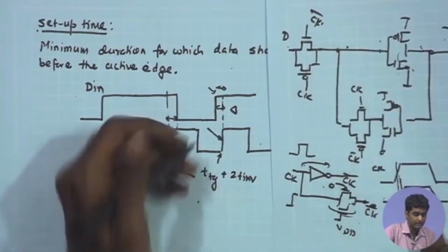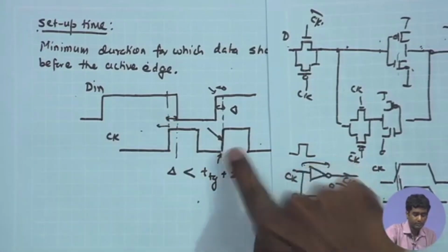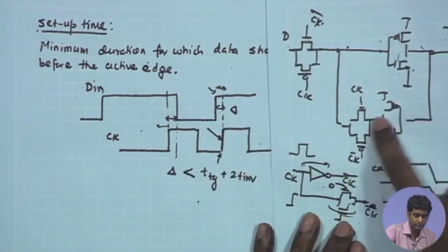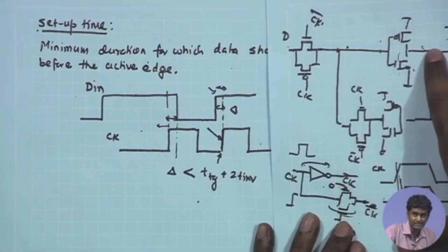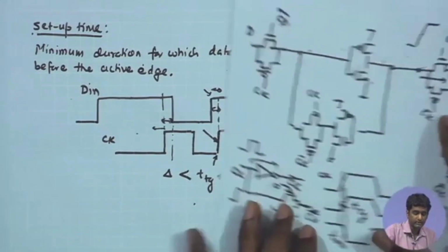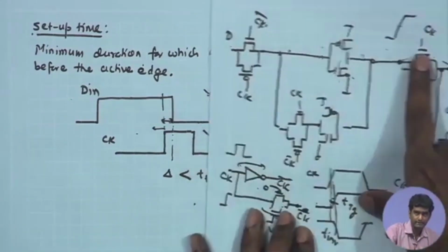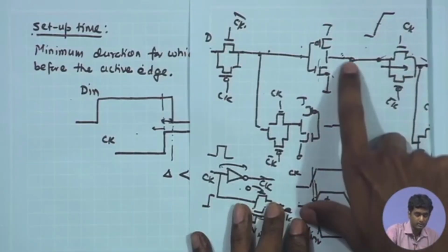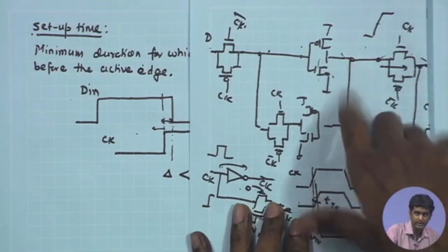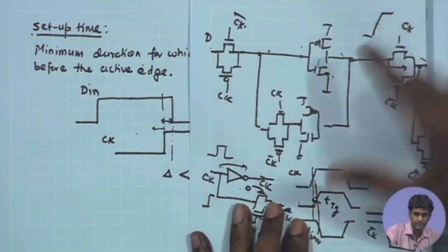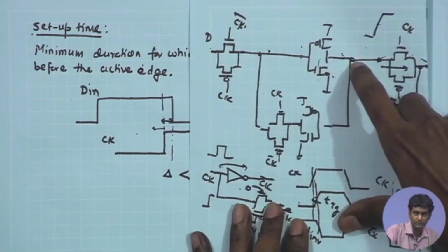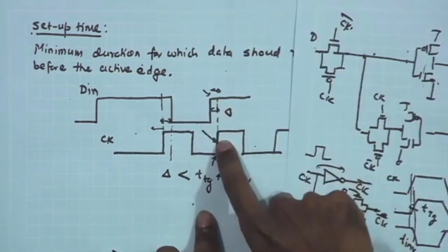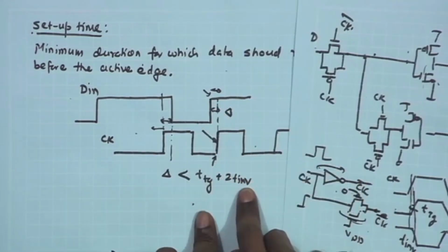second inverter, that means before the positive edge of the clock, when this turned off, the data has not propagated fully in this loop, data has not been stabilized at this node, and as a result, when the Tg over here gets off and this particular clock over this particular Tg over here gets on, the data at this point can end up having the reverse polarity, the opposite polarity, and therefore, we will expect that rather than sampling a high level, it can end up having a low level.